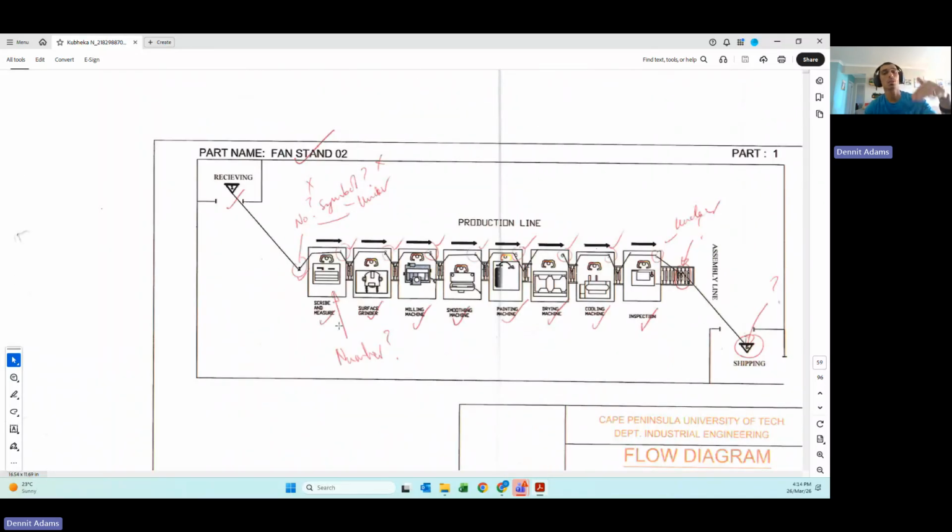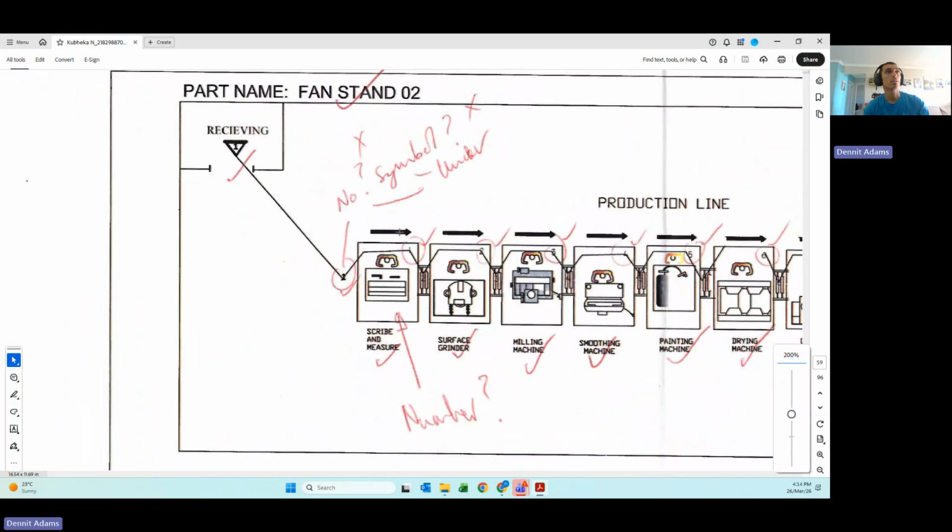So she's listed all her manufactured process charts. Now the related flow diagrams come in, and she's designed this very beautifully on SolidWorks. So you see here, it comes from a receiving stores. That's the triangle there. And the arrows you will duplicate again with the operations. So you must have the relevant symbols. So if the arrow dictates transport or movement, you're going to put transport number 1.